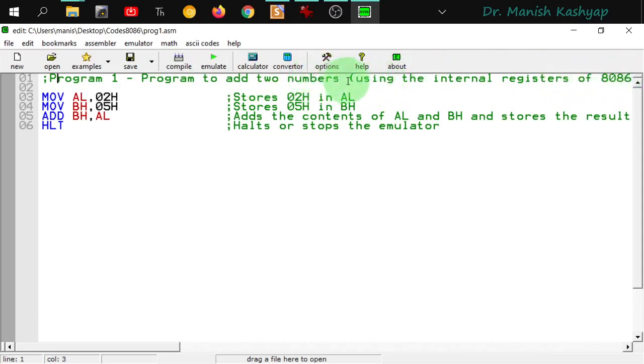Through this program, we will understand a couple of differences between 8085 and 8086. As I told you, the accumulator here is a little bit free. So in this program, we will see that by default, the calculation result will not be stored in the accumulator. It will be stored in the registers which we specify, right? What we are going to do is, from the programming model, we take only 8-bit data here. We take 8-bit data and keep it in the AL register and BH register.